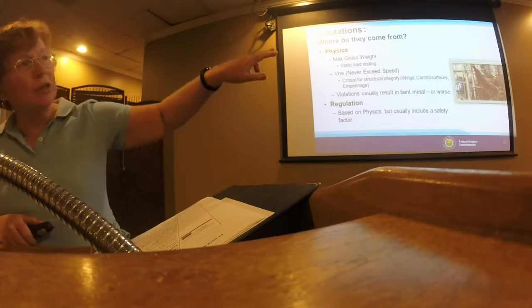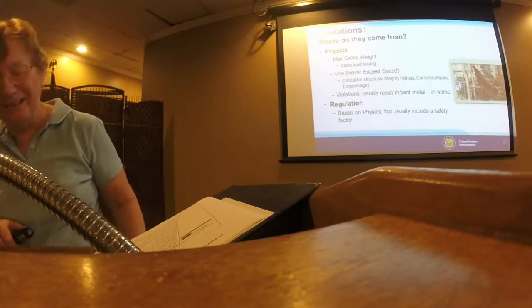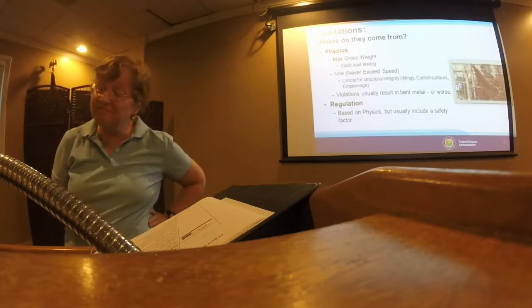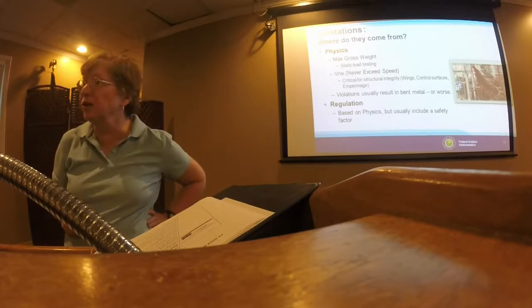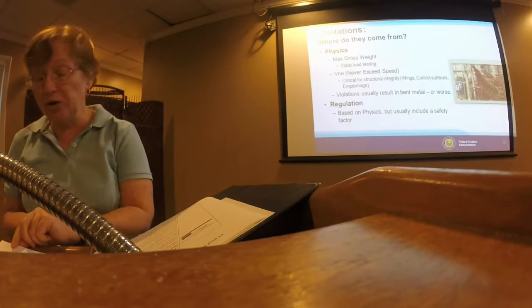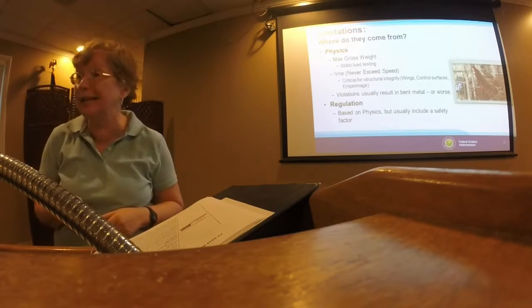If you see the wing at that angle, you probably have a problem. But for our little guys, they just loaded it up until it failed. Max gross weight, of course, is determined in reference to that structural testing.